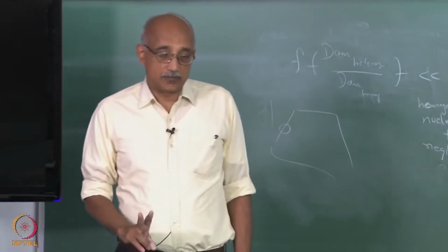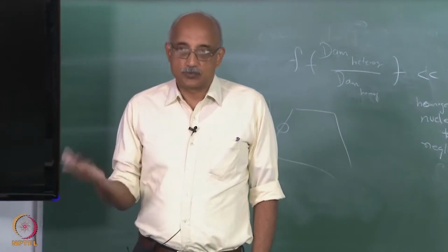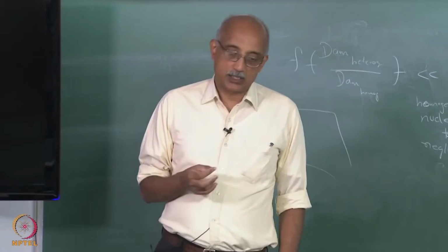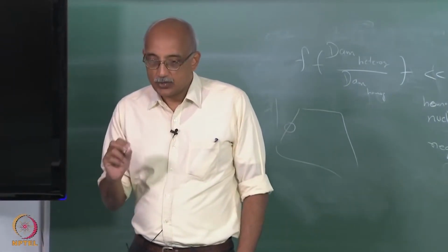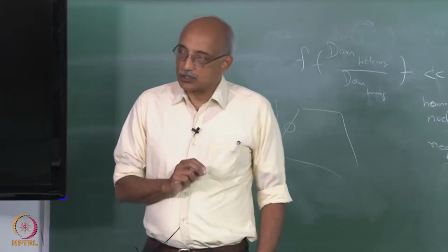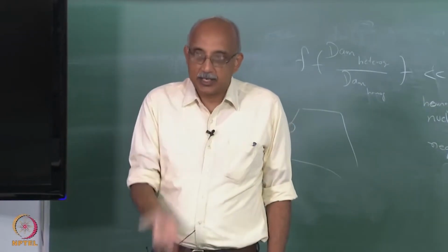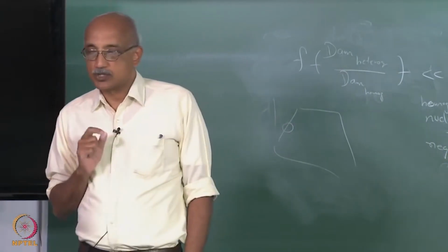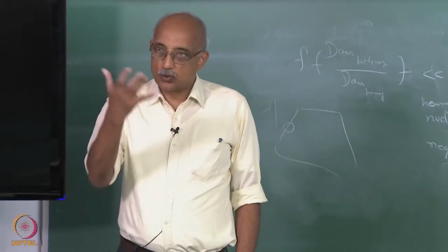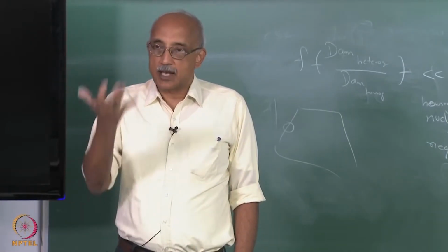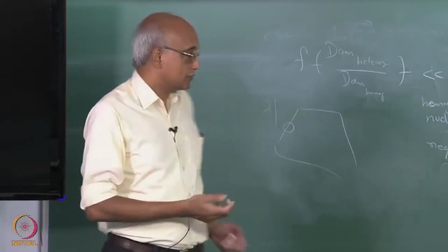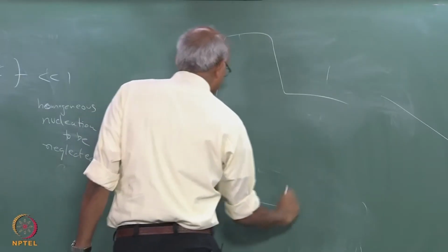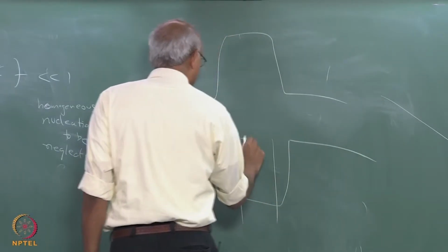But the second mechanism that leads to aerosol deposition is inertial forces, inertial impaction. Now, depending on if you are trying to promote aerosol deposition, you want to provide essentially line of sight deposition. In other words, inertial deposition happens most effectively when the source of the particles is located directly upstream of the substrate. So, for example, let us say you are using a conventional flat plate type of CVD reactor,